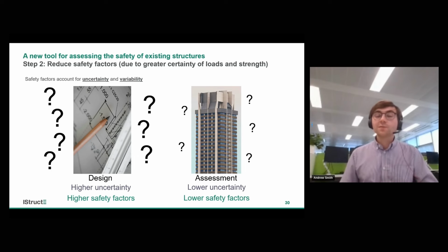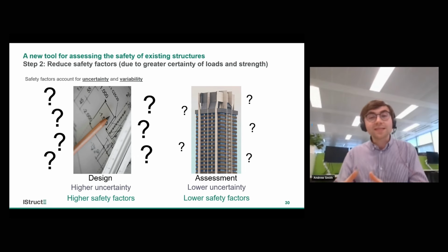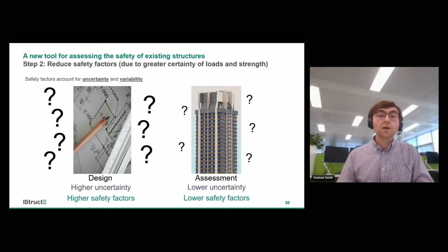And so as a result, if we compare the design scenario to the assessment scenario, for design we might expect higher safety factors, and for assessment, if we've done lots of investigations and we really properly understand our structure, then there should be an opportunity to reduce those safety factors. And that's what the tool that we're providing gives guidance on.